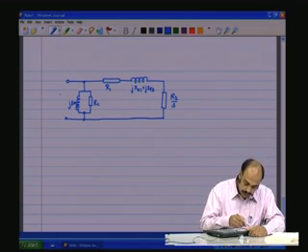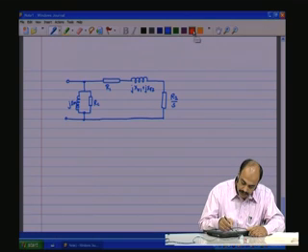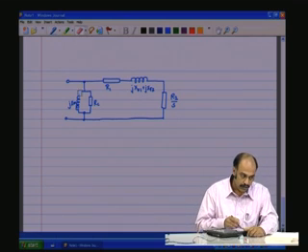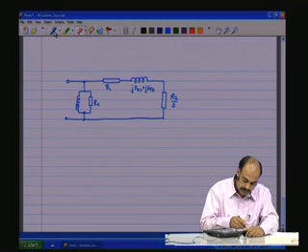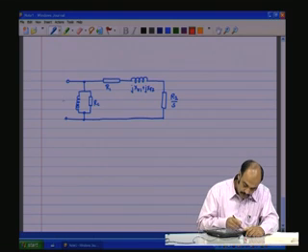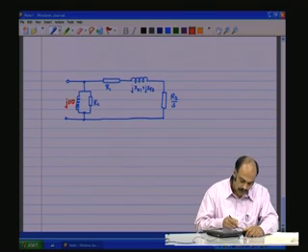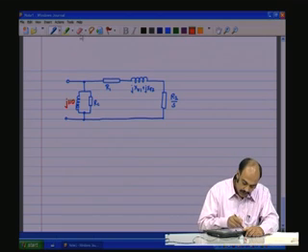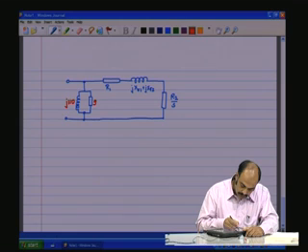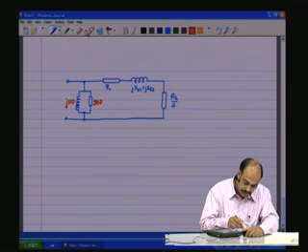Now what we shall do is give some typical values of a motor to these. We shall give the magnetizing reactance a value j110. The value for the core loss component, 900 ohms.